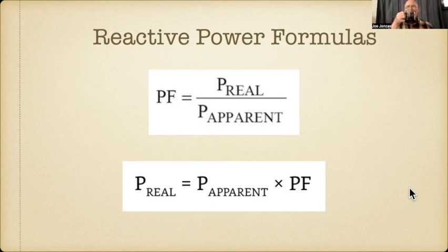So once again, real power we can calculate because we have those formulas that we learned in the beginning. Correct. But apparent power, where do we get that from? Apparent power is simply the voltage. If you have a voltmeter and an ammeter and you measure it. Okay, so again, it's a measurement. Yeah, if you're dealing with a motor, you'd probably measure 120 volts AC. Then you had an ammeter clamp on and it measured 10 amps. That is the apparent power.